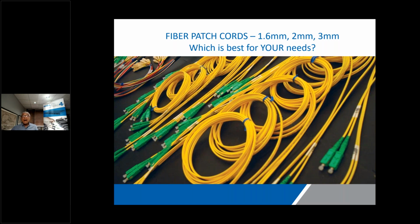Patch cords come in thousands of varieties. If you're going to buy patch cords, obviously you need to know, is it single mode, is it multi-mode? Is it simplex or is it duplex? Danny will show you that. What kind of connectors do you want? Are they the same on each end? Are they different? What type of polish do you need in the connectors? Because as you can see here, you've got green plastic housings, which typically is going to designate an APC. And we have a couple of slides on that in just a few minutes.